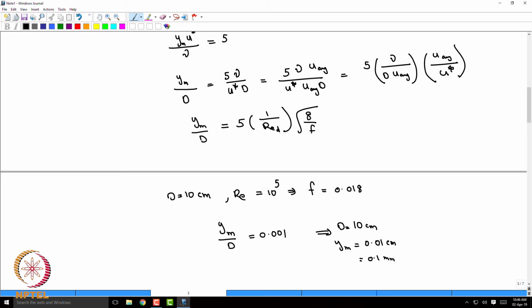Yeah, so because it affects the wall layer, the other layers are on this layer. Because of the continuity, yeah. So for example, you need to maintain some stress balance that will get disrupted. So the entire thing will get disrupted. In fact, the log layer will remain as a log, but the arguments and the constant, everything will get changed. Therefore, the friction factor expression that you have gotten should be relooked at in the context of a rough pipe. Yeah.